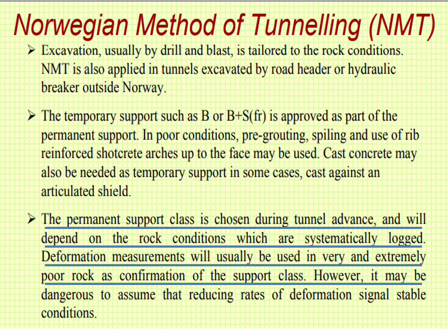In the Norwegian method of tunneling, excavation, usually by drill and blast, is tailored to the rock conditions. NMT is also applied in tunnels excavated by roadheader or hydraulic breaker outside Norway. The temporary support such as bolt or bolt plus fiber-reinforced shotcrete is approved as a part of the permanent support. In poor conditions, pre-grouting, spiling and use of rib-reinforced shotcrete arches up to the face may be used. Cast concrete may also be needed as temporary support in some cases, cast against an articulated shield.